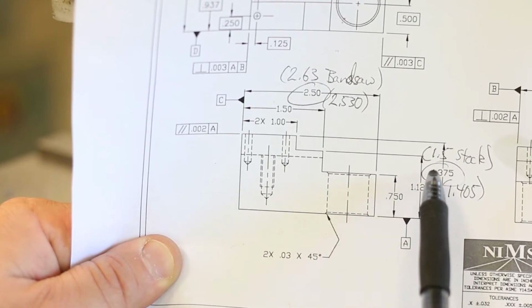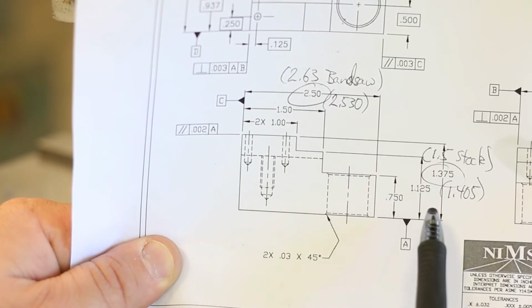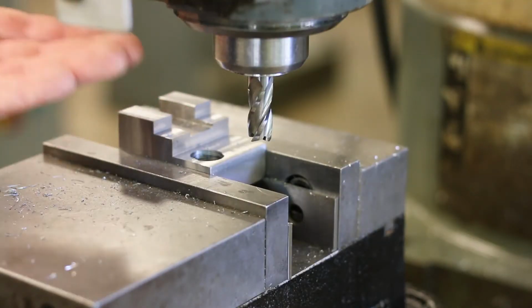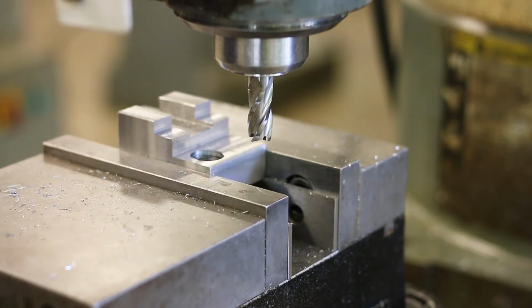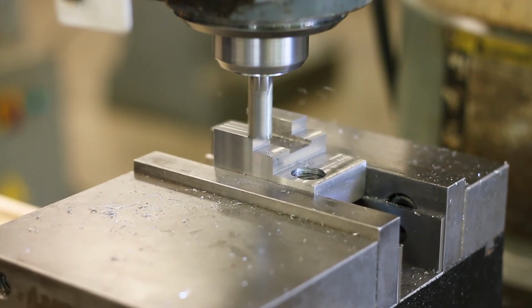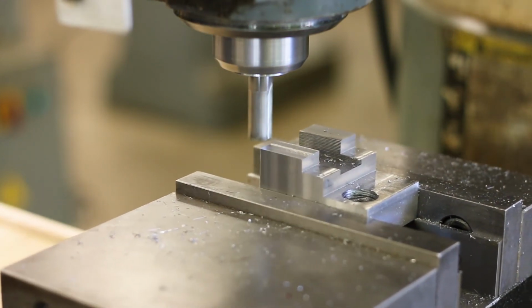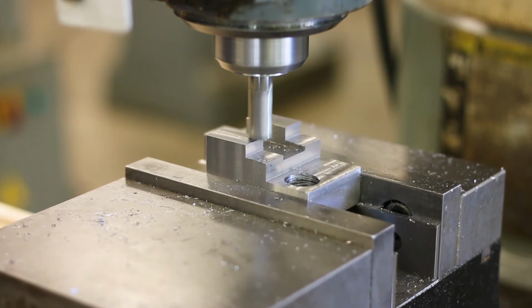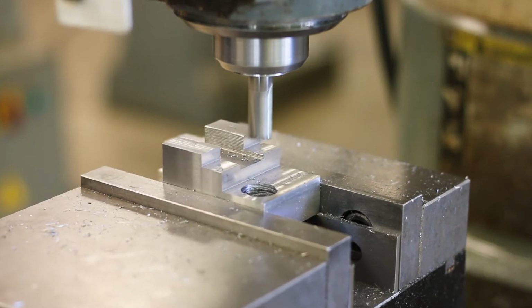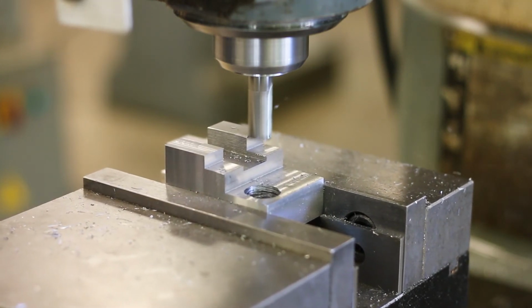We're at 1 inch, 394 and a half right now, so we need to take 19 and a half thousandths. So I'm going to go ahead and take that all in one go. So on the knee, I'm going to go 10, 15, 19 thousandths right there. Let's take a cut across those surfaces. Okay, and without moving the depth at all, either on the quill or on the knee, I'm going to come over and I'm going to do the other side.